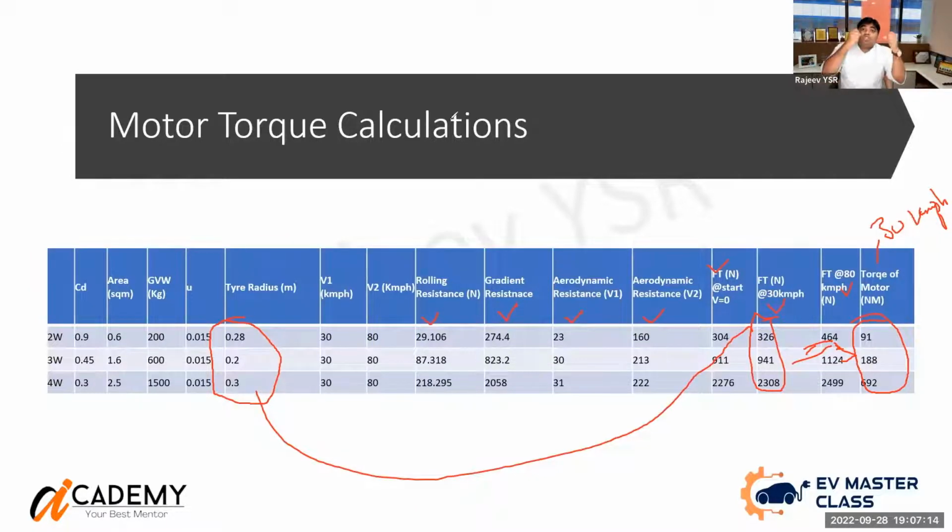Now, how long should it run? When you decide the time factor, when you say that it has to run, say for 3 hours or 4 hours or 5 hours, when you multiply that 4 kilowatt motor into 4 hours, that is where you get 16 kilowatt hour energy. And from the 16 kilowatt hour energy, you get the specifications of the battery. Is it clear to you, or shall I repeat? Please respond.